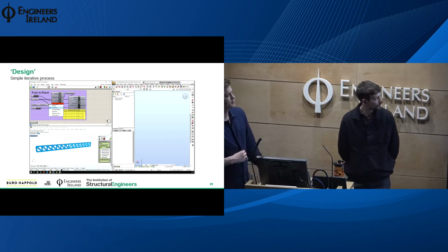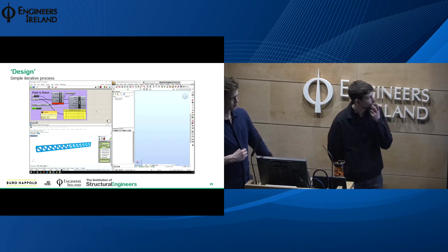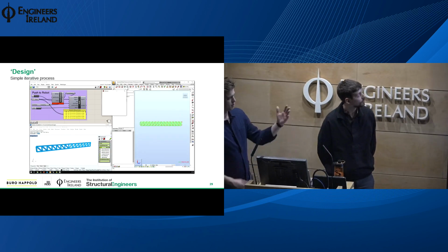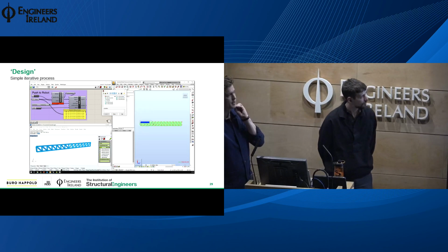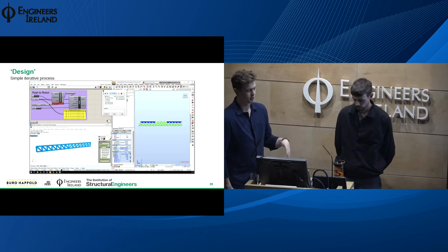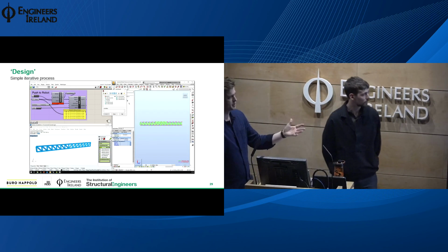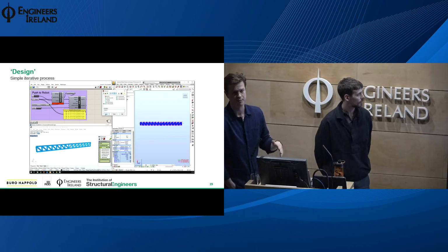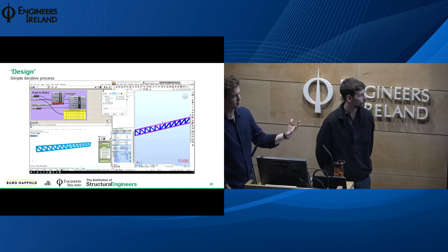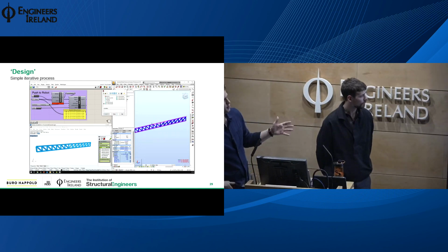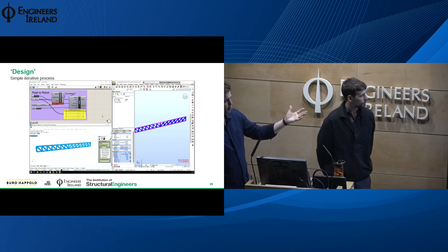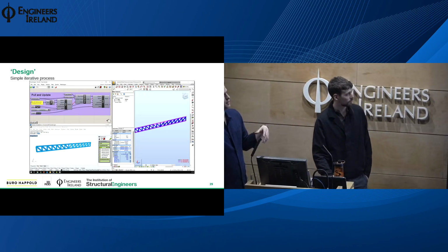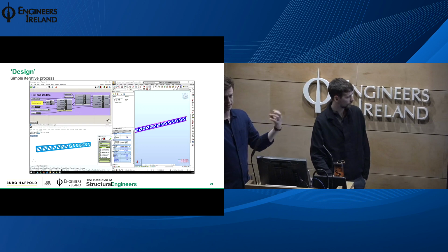And then next, what we have here is design. So design creation, subframe analysis. On the right hand side there we've got Autodesk Robot again. Hopefully an environment that a lot of people are used to. I like to build up my models traditionally within Robot as opposed to tracing them onto the background of a CAD file, which some people do. But on the left hand side here we've got the Grasshopper script on top, we've got the Rhino CAD file on the bottom, and what you're seeing here is the pushing and pulling of that data.